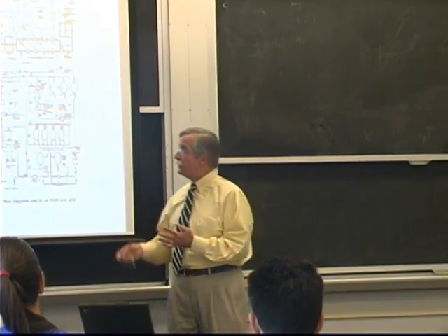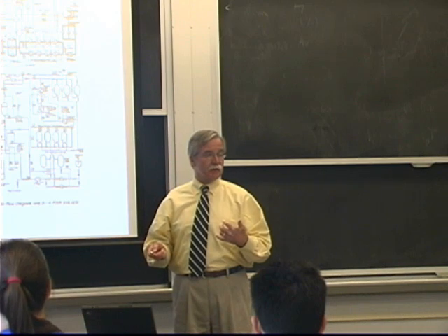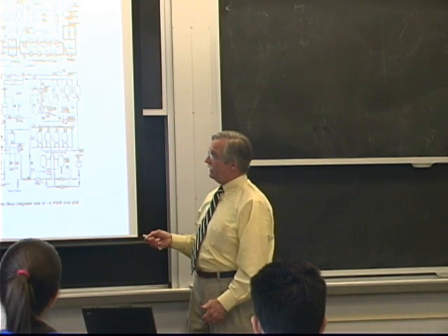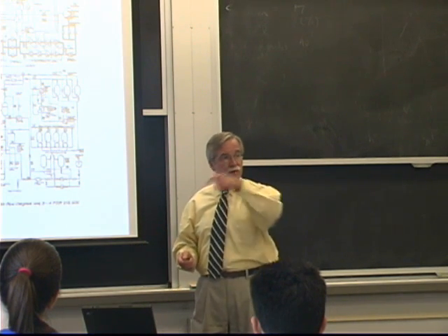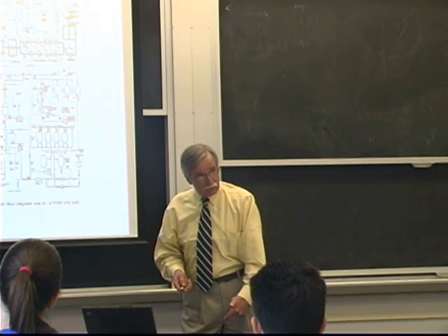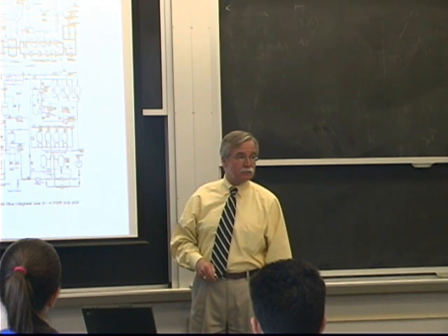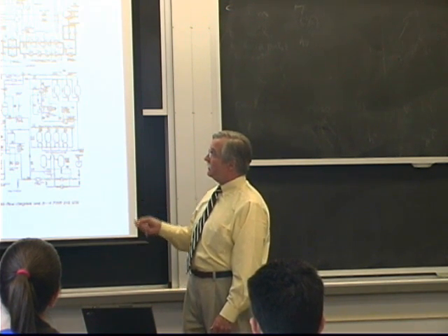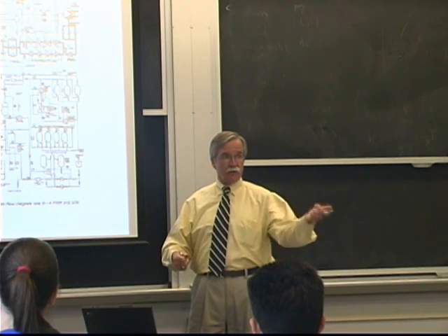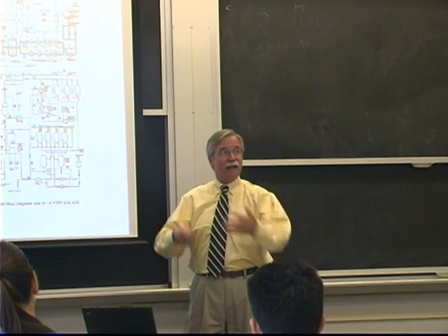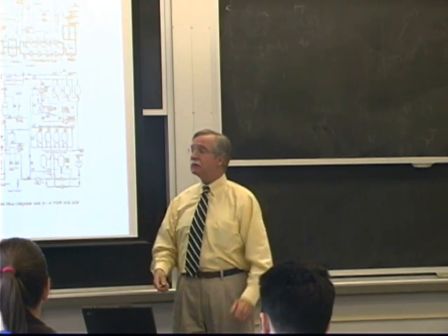EPR is a bigger version of this with more redundancy. It's more robust. And they've added a core catcher in the bottom of the containment. So in the event of a fuel melt through the vessel, they'll be able to say that we cannot have a recriticality, and we can manage the pressure spike. So it's a much more robust basic reactor. I don't know if you heard David Lochbaum when he was here. He likes the EPR because it's more robust, more rugged.